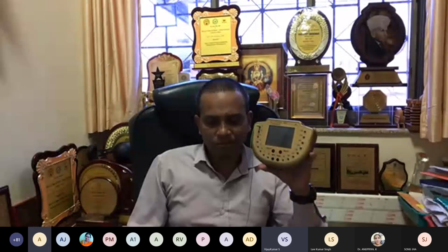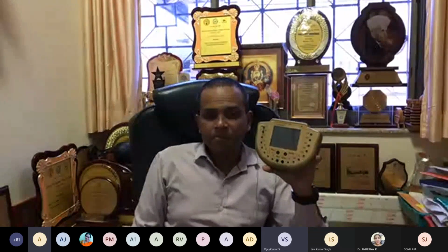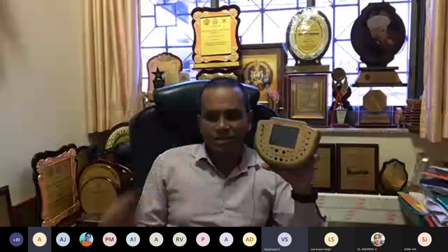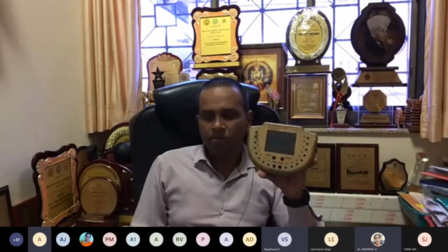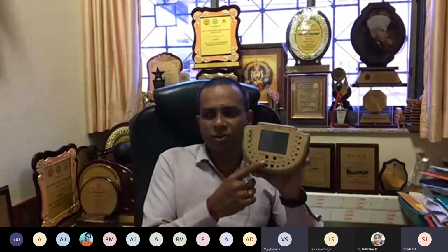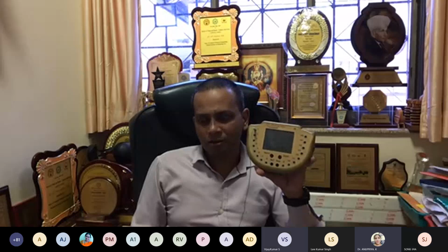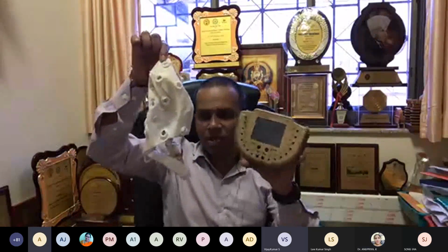So finally, you're not going to connect these two to the computer. Only the actual electrodes you're going to connect. Don't worry about that. Now tell me, if my application requires two channel data, which means two different brain signals, how many wires do I have to connect to the amplifier? You tell me. Two, sir. Two plus two, ground and reference. Total four wires you have to connect. Four wires, both sides, to the amplifier and to the EEG cap.